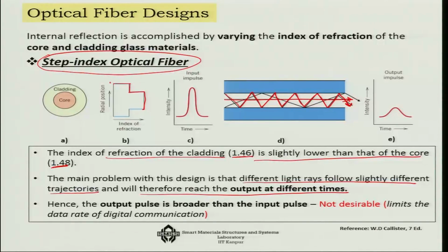So this slight delay will create, if this is my input impulse, an output that would look like this. That means the output pulse will be broader than the input pulse, which is not desirable, because if this happens, it actually limits the data rate of digital communication.